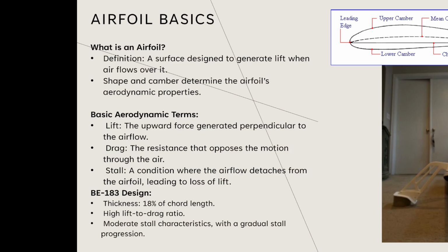This ratio gives it a really good high lift to drag ratio, although it's not too aggressive of a ratio. So if that upper camber was more aggressive, say 25% of the overall chord length, it's going to be hard for the air to stay attached to such a curved surface. So when it gets to that top point on that upper camber surface, it detaches. And when that air detaches, that's called stall. And when you get to stall, your airfoil is doing nothing. It's not giving you anything, it's just hurting.